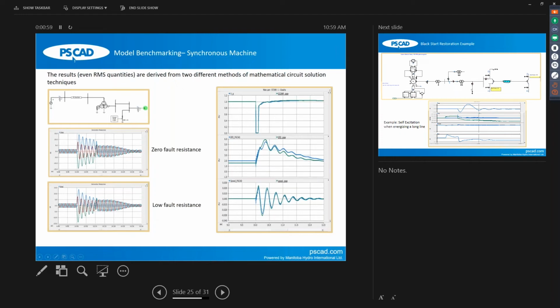So in this case, I think the red phase experiences a current zero because it's symmetrical. So the fault on that phase would be cleared, but the other phases would continue to conduct towards the fault until they come across the zero crossing, right?